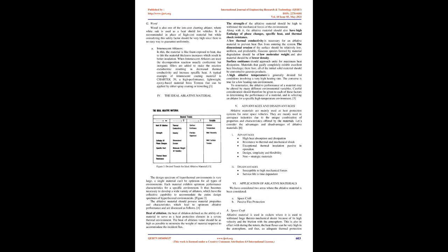E. Charring ablators. Charring ablators are widely used in a wide range of thermal environments, compared to subliming or intumescent ablators, because of the ability to withstand much higher heat flux. Charring ablators are often used in combination with subliming and melting ablators. Carbon phenolic, known as high-density charring ablator, contains high-density reinforcements to improve shear resistance, whereas low-density charring ablators, epoxy novolac resin containing phenolic microballoons, and silica fiber reinforcement are used only in low shear environments.